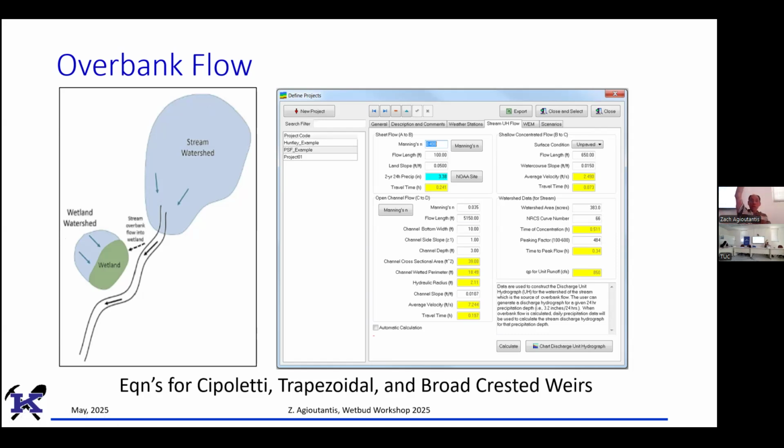Precipitation is what goes into the wetland directly from above. So precipitation is the amount of rain that goes into the green area. Runoff is rain going into the blue area here. Some of it will infiltrate and some of it will actually run on the surface. This is runoff. This is also an input, surface flow that goes into the wetland.